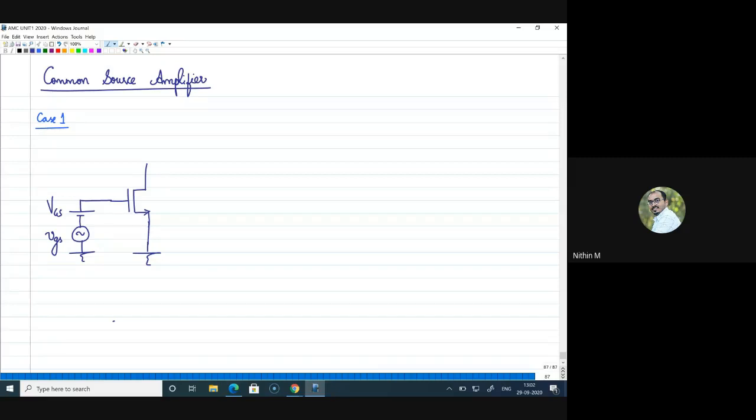Now, gate DC is done by this DC source VGS that I am connecting on that side. Now at the drain side, I cannot directly connect this to VDD or the supply voltage. So what I can do on the other side is I can connect like this, right? This is what we have seen before, VDS. But if I do like this, I cannot take a signal, or I cannot get any variation of the signal that I'm applying for the VGS, right? I can even mark like this, but how will I get the variation?